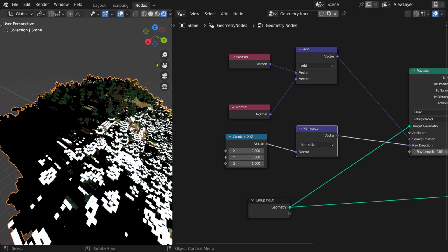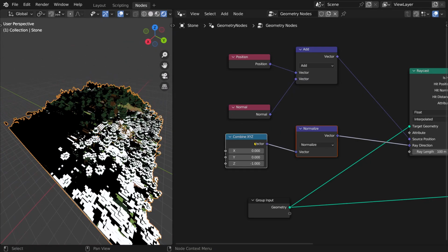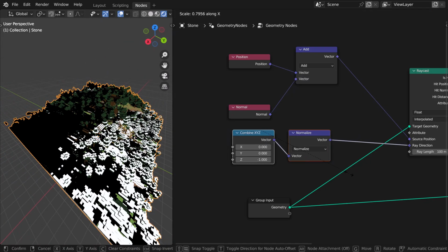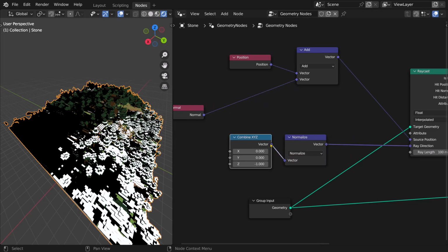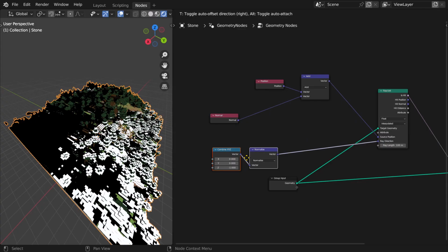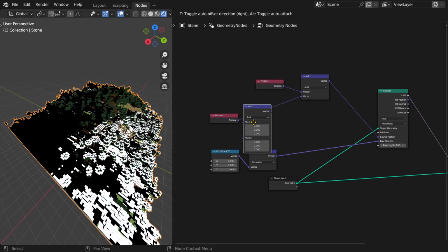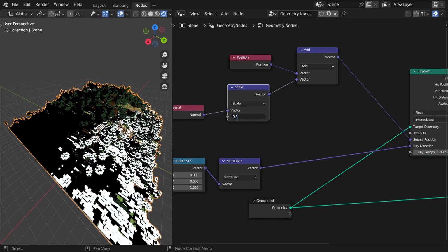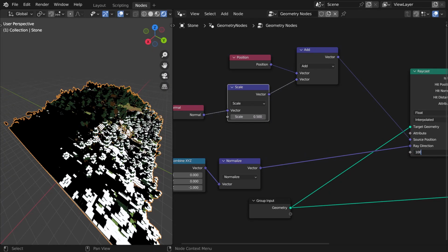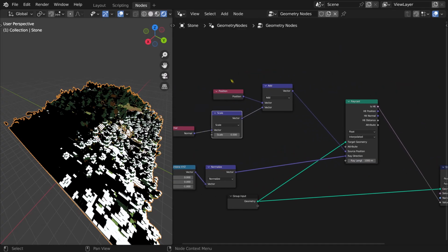Well, as you can see now, before fixing anything else, we need to adjust and organize the nodes in geometry nodes. Now we will organize the spread of the normal rays on each face, and to do that, we control the size of this ray using a vector math node set to scale. Set any value here that is suitable for your world right now, and make the ray length very large, about 1000.